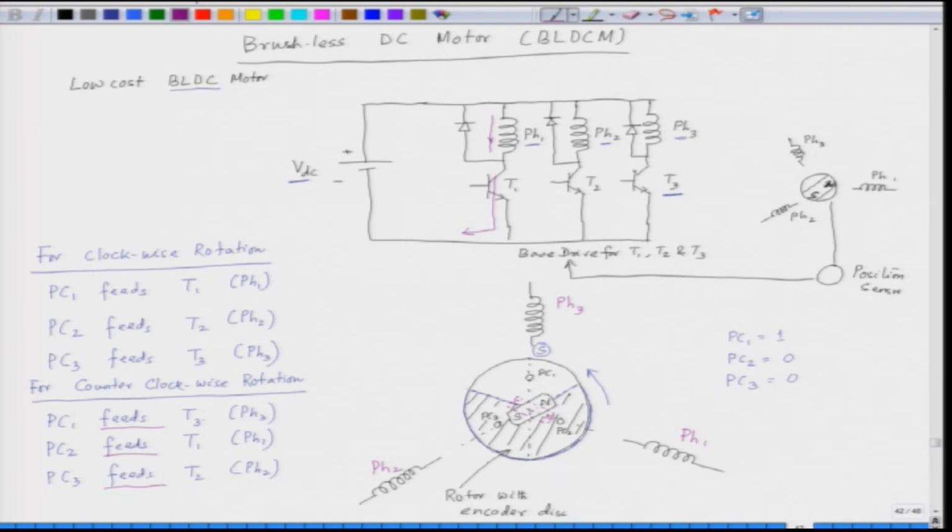So, this is a low cost motor. So, what is the application here? There is no brush, the rotor is a permanent magnet, the stators are concentric winding. The stators are not distributed winding, stators are concentric winding. These motors are very popular in computer fans. In a computer power supply, we have a switch mode power supply, we use a fan, that fan is a brushless DC motor. There is no AC there, we are applying a DC to the motor, it rotates for years without getting damaged, because there is no brush. Since there is no brush, there is no maintenance.